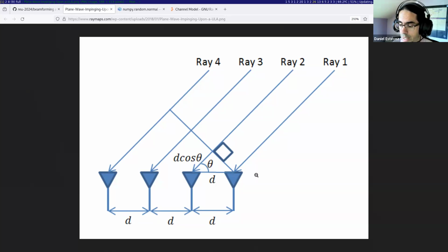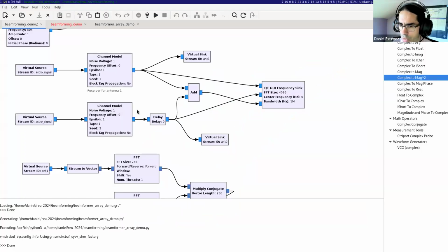So we can do beam steering and point one synthetic beam to each of the stars which are within the primary beam of the antenna. The primary beam is what is determined by the physical size of each of the antennas in the array. So that's the point of this demonstration.